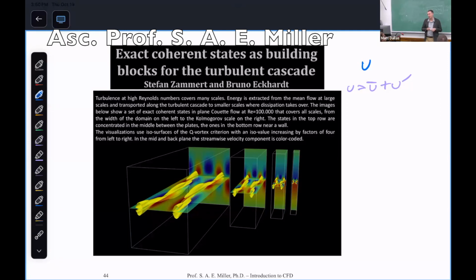It's called turbulence modeling. I teach a whole class on it next semester where we go from the very beginning of CFD and develop turbulence models. We even create a basic CFD code with a basic turbulence model for incompressible boundary layers. And that's all of MAE, the mechanical and aerospace department. So the idea is I'm not going to predict the actual fluctuations of turbulence. I'm going to predict the statistics.